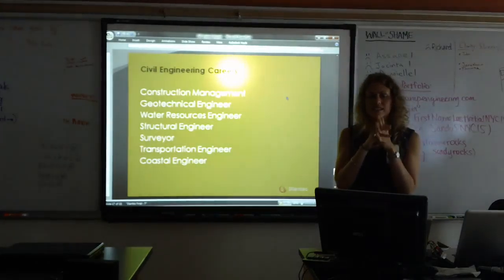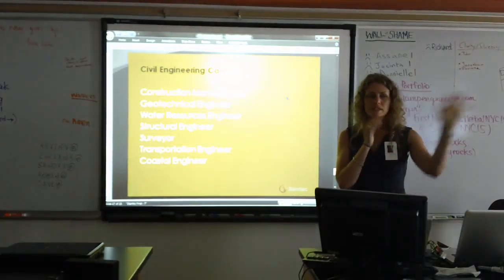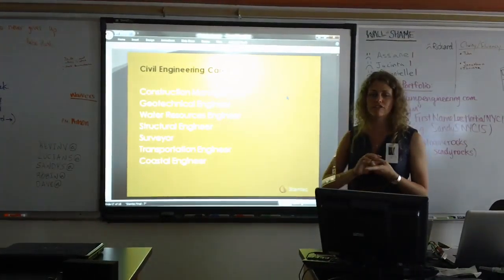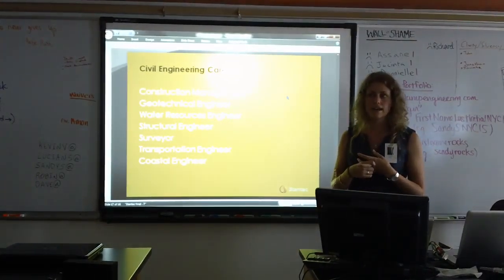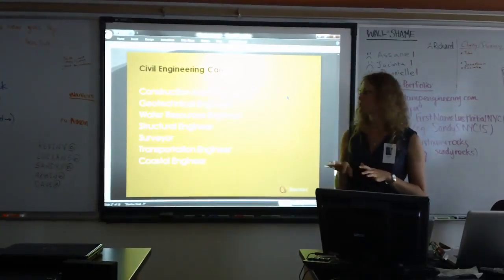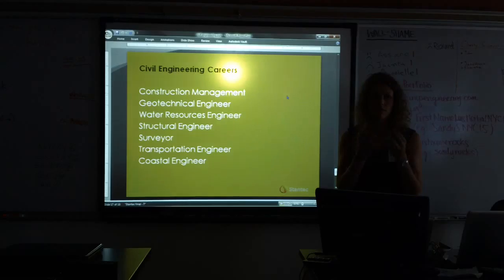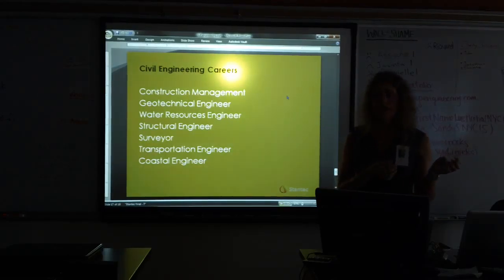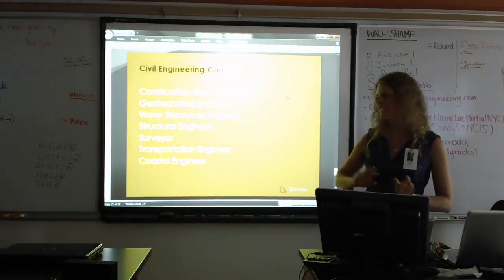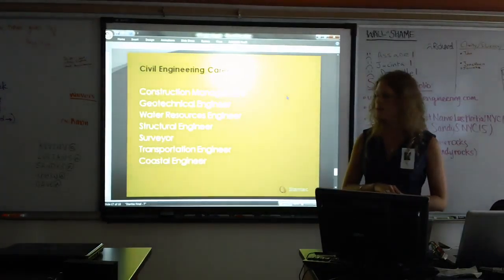So what that is, it's taking measurements from a base point, and it's taking the measurements, distance and elevation, of curb heights, hydrants, building lines, anything in the area. And after the surveyors gather all that information, they're able to put it into a program like AutoCAD, and then I get those drawings, and then I can design off them. So that's like the first thing you do when you get a project.